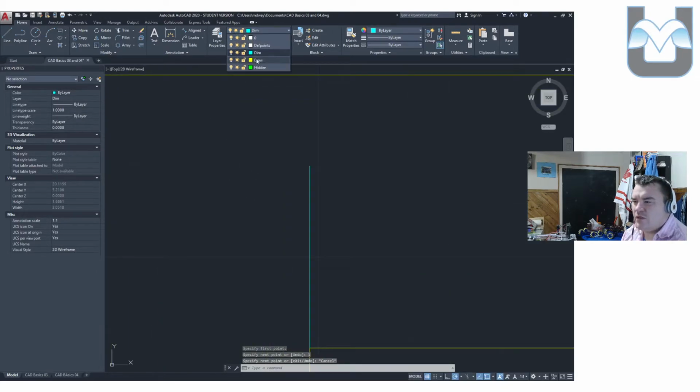Now the triangle itself, the easiest way to draw it is by using the polygon tool. Polygon tool actually lives up here above where your rectangle tool is with a little pull down menu, and then it's going to allow me to actually select the number of sides, triangle, 3 sides. Okay, and I'm going to specify the center of the polygon, and I'm going to create inscribed in circle. We're going to do the first one here. That's going to give us our triangle.